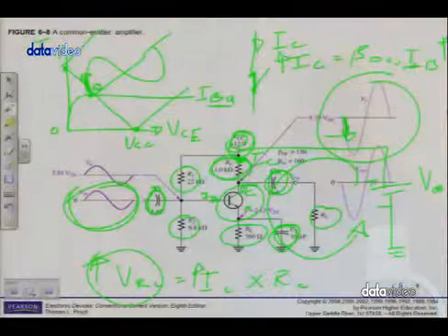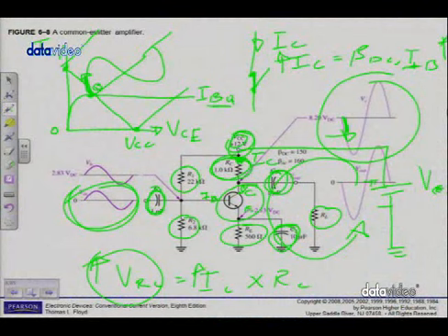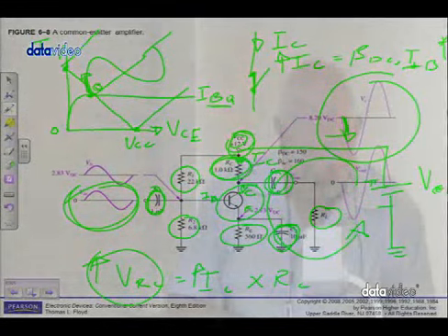It says, the output signal is 180 degrees out of phase with the input signal. It starts with that statement. As the input signal voltage changes, as I explained, firstly it increases now. It causes the AC base current to change, resulting in a change in the collector current from its Q point value. If the base current increases, the collector current increases above its Q point value, causing an increase in the volt drop across RC.